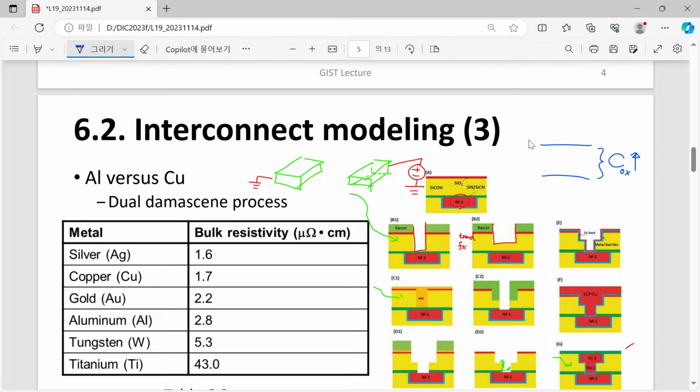It is because for a given gate voltage, we wanted to maximize the number of inversion charges as much as possible, because we wanted to maximize our drain current level. So that was a common way. Instead of increasing the voltage, corresponding to VDD, by increasing the oxide capacitance, we can increase the drain current. That was the situation.